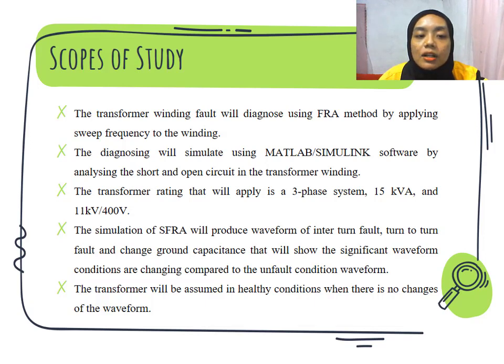The simulation of SFRA will produce waveforms of interturn fault, turn-to-turn fault, and also change in the ground capacitance, which will show significant waveform changes compared to the unfault condition waveform. And lastly, the transformer will be assumed to be in a healthy condition when there is no change in the waveform.